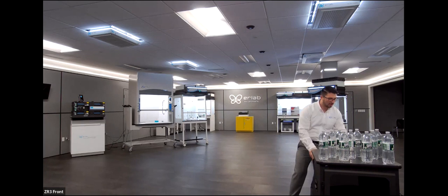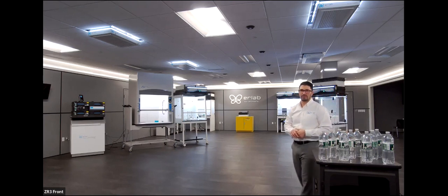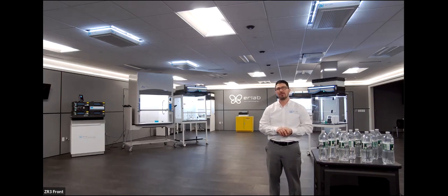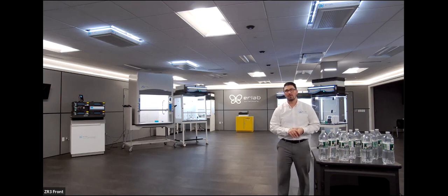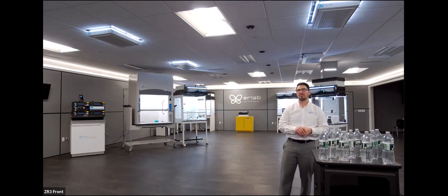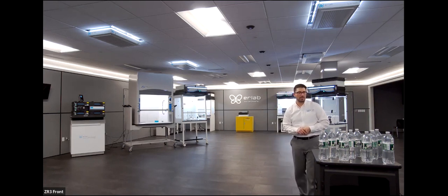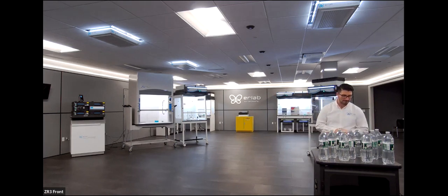If I was installing this in a lab, would that change the amount of volume of air to be processed? It depends. If we deal with labs that do histology, pathology, where they have heavy use of xylene, which is very odorous, extremely noxious, and they use a tremendous high volume of it, yeah, we would probably increase the amount of Halos that are required at the molecular level, and probably increase that for 1 every 5,000 cubic feet. Again, it depends. It's very variable, dependent upon the facility. Any other questions? We got time for about one more.